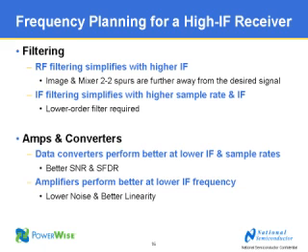So if we take a look at the filtering, the RF filter and the IF filter are actually both much easier to implement for a higher IF. Similarly, the IF filter actually does better with a higher sampling rate on the ADC. Yeah. So you've got on one hand the filters require high IF and high sampling rate.